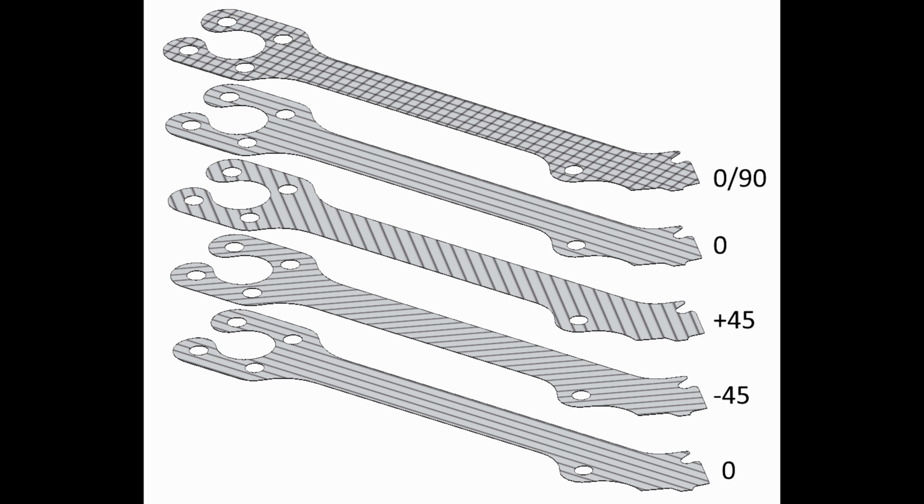I see. Interesting. And that means we can have more fibers along the arm without adding the weight of the 0 or 90 degree direction. That's so smart. We can have higher strength with the same fiber. Yeah, with lower weight or whatever you want. You're just using the 90 degree fibers in more useful directions. Exactly. This approach you can do with any fibers. It will be better even if you have T300 or whatever.